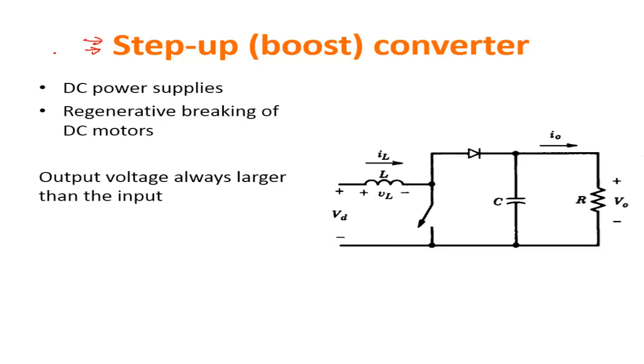As you remember before, by construction the output voltage was equal to the input voltage times the duty cycle, which is always smaller or equal to 1. Okay, if you want something that is larger than 1, you need to change the circuit, and this actually can work.